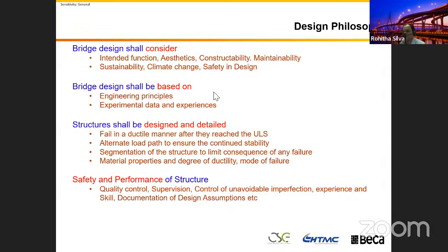When you design the bridge, the philosophy is it should serve the purpose, should be fit for the purpose, the functional requirement. Not only that, it should be aesthetically pleasing, buildable, maintainable, and sustainable. I think today sustainability is one of the key things. If I may remind you, I gave you the example: in New Zealand, the government decided to use timber as a construction material instead of concrete and steel, considering the sustainability requirement.